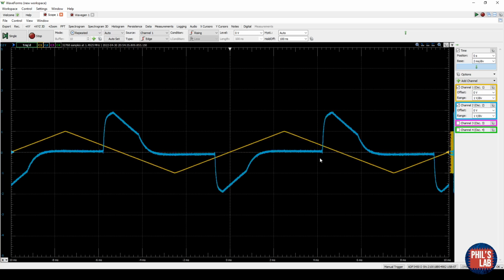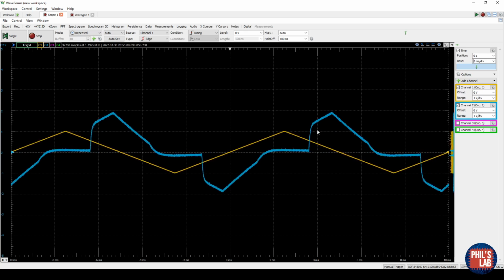So you can see there's far less sharp transitions if we compare that to the very simple noise gate. Here we have an exponential increase in the release stage and an exponential decrease in the attack stage. So this should give us a better sounding noise gate. We'll have less harmonics and less distortion. I can also play around with my threshold, for example. So if I move my threshold around, you can see I'm letting more of this triangle wave pass.